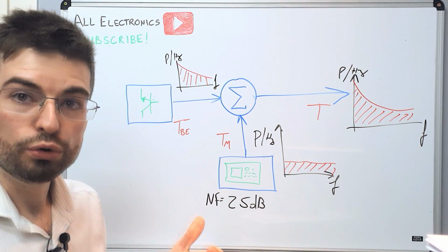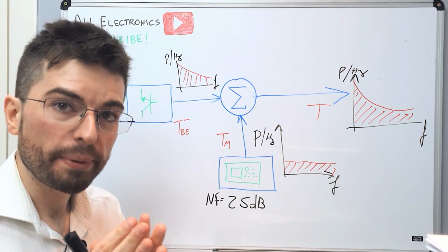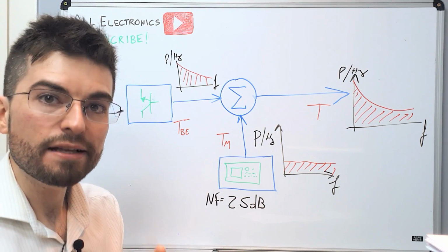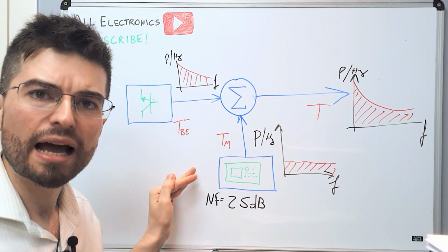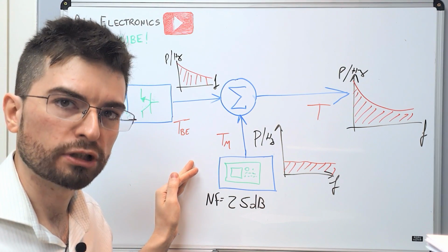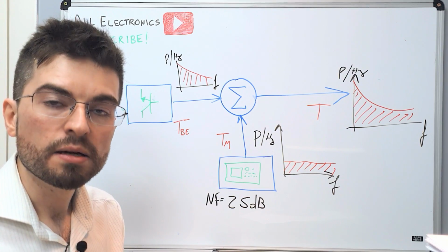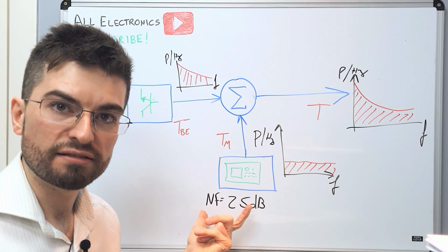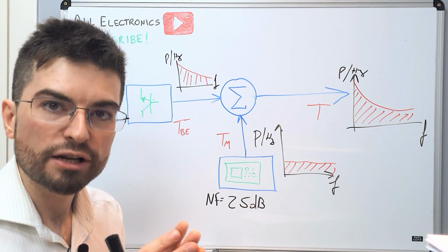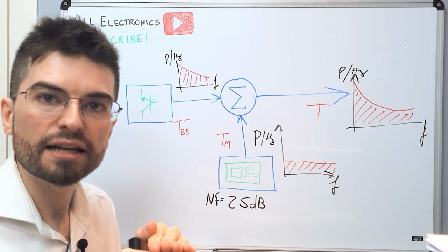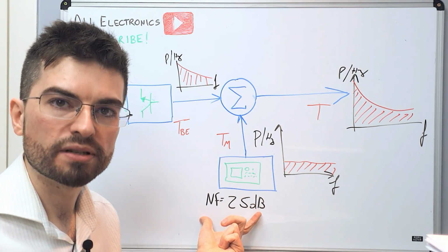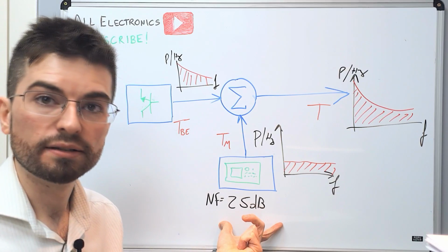One thing we can do that helps a little to compensate, it's not perfect, is to measure the baseline noise floor of the spectrum analyzer, doing exactly what we did with the automated test, but connecting the spectrum analyzer to a 50 ohm load to measure the baseline noise floor of the measurement setup, and we store that measurement.